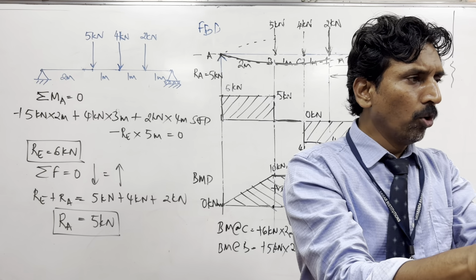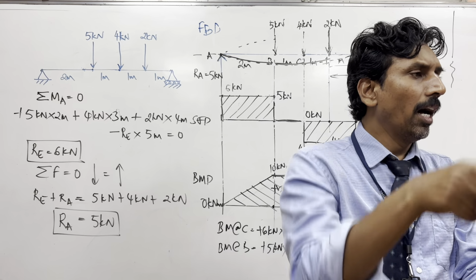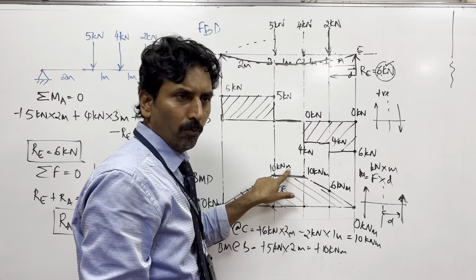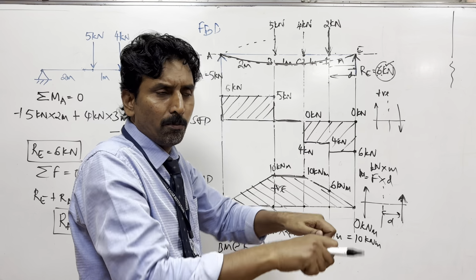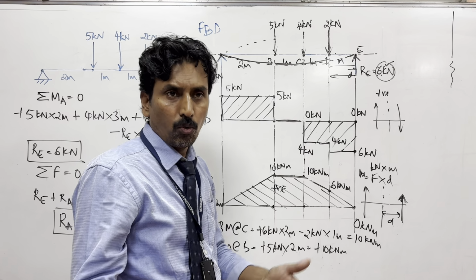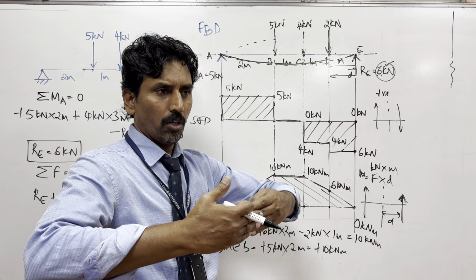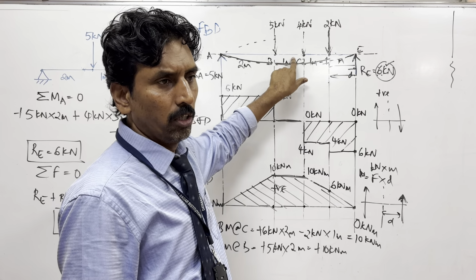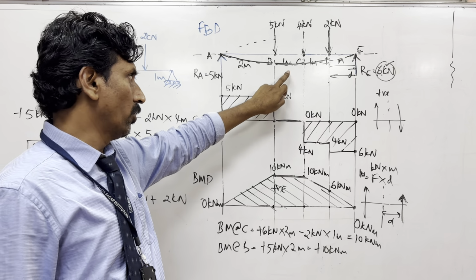If you try to bend more, suppose you apply more moment, then the scale bends with more curvature. In the same way, if you apply more bending moment, the beam bends more. So you'll have a shorter radius of curvature where there is more bending, and a larger radius of curvature where there is less bending.